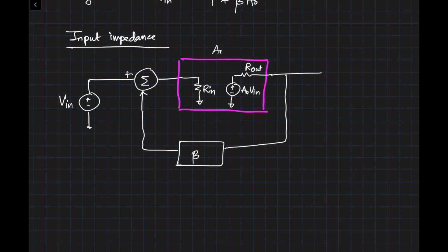Since we have series connection at the input, whatever current Iin is going in will go here, since it's a series voltage connection. Other assumption we are making here is that this feedback network is ideal and it's not loading the output branch. If you remember in the previous examples, the resistances R1 and R2 were large so that they don't modify the gain of the amplifier by themselves. So in this case, we can write the equations as follows, and then let's focus on the final result.